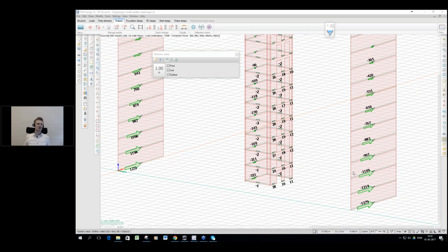The maximum of load combinations is very good for bars, where you have all the different sections, and one node can have one load combination that determines the cross section, and the other node can have another. There, it really makes sense to look at the maximum of load combinations. This is what you must do, and this is what the program does. But for the overall stability calculation, that's not good. Don't do that. Look at the separate stability load combination results.